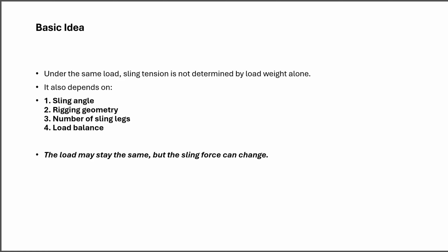In rigging, many people first look only at the load weight, but this is not enough. The same load can create a different force in the sling legs when the sling angles or rigging geometry changes. This is why rigging safety depends not only on load weight, but also on force distribution.